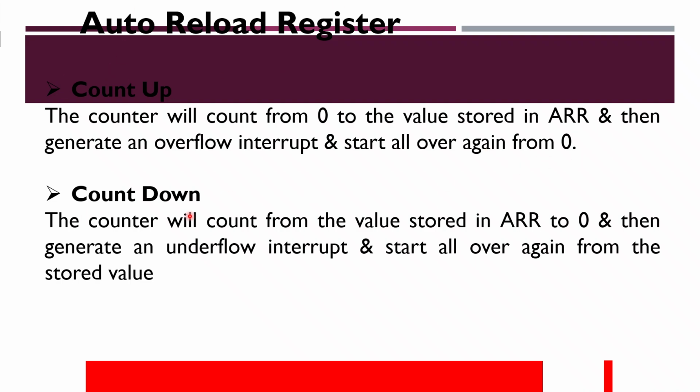So what is countdown? Actually the opposite. The counter will count from the value stored in ARR. So in the auto reload register something is actually stored, right?